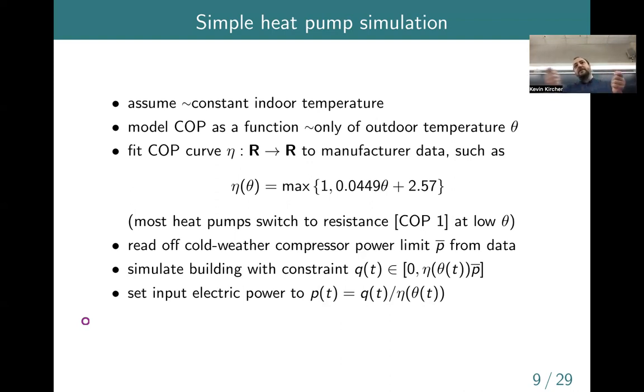So the COP as a function of compressor speed typically drops off at very low compressor speeds and at very high compressor speeds. And there's a sweet spot in the middle where COP is typically maximized. Below a certain speed, typically around 30%, variable speed heat pumps will switch from modulating continuously to duty cycling, switching off and on. Those cycling effects can have some further efficiency losses, so you can get a pretty steep drop off in efficiency at the very low end.